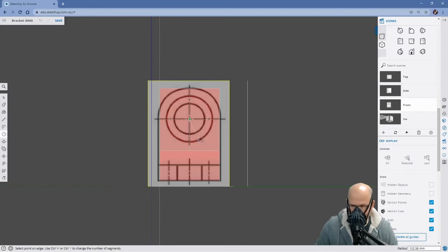Probably about right there. Now, I want to make sure that when I'm creating the circle, notice my radius. It's good practice to line that radius along one of the axes that are there. Otherwise, your circle can be somewhat skewed. Remember, it's not really a circle. It's more repeated line segments. Okay. So, there we go. All right.